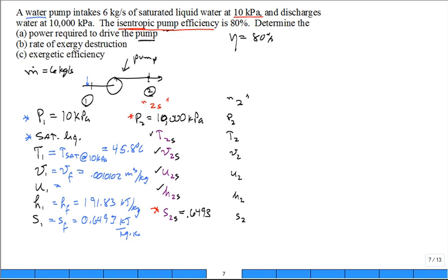It's kind of a weird way of doing it, but I'm going to try and tuck it in over here. 10 MPa, T, H, S at 40 degrees and at 80 degrees. I know I'm running out of room. Here I'm going to put 80 degrees C right there. I have H in kilojoules per kilogram and S in kilojoules per kilogram Kelvin.